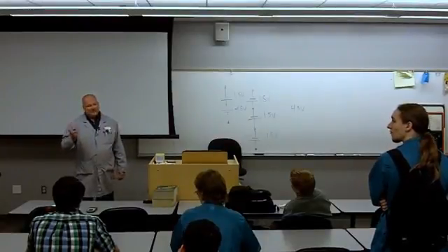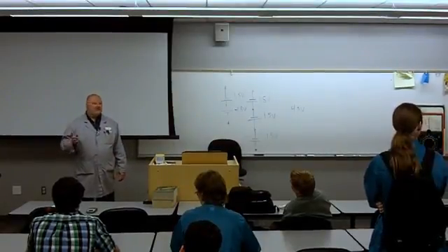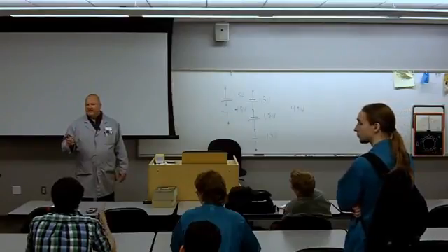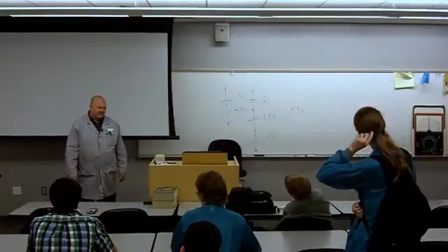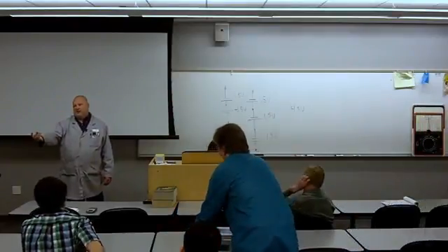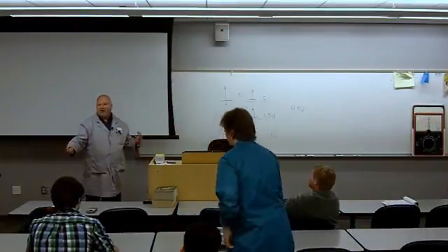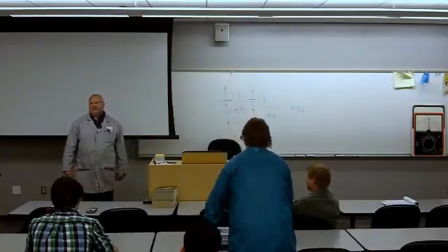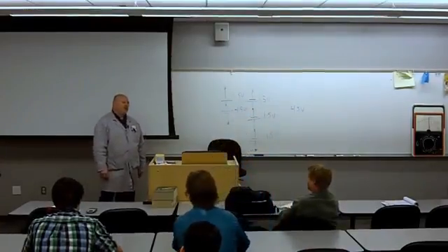FM transmitters, different. If you're in New York City, where do you want to put an FM transmitter? Top of the Empire State Building. Why? Because it's the highest. It doesn't have as much to do with ground. You still need a good ground, but it's not as essential as for low frequency transmitters. So ground is important, folks. We're going to talk more about it.